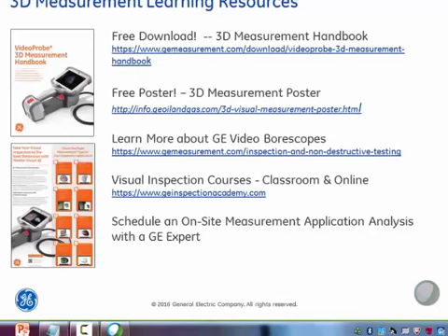Yeah, so I think we'd be happy to even come out and do a demonstration for you. I think you'd be very satisfied. We can test it against knowns, but that particular size that you're talking about is very much in the sweet spot of what we can do, assuming you can get close enough to it, which with our video borescope products, you need to be somewhere around an inch or closer. And the smaller the defect is, the closer you'd want to be, as Clark had demonstrated.